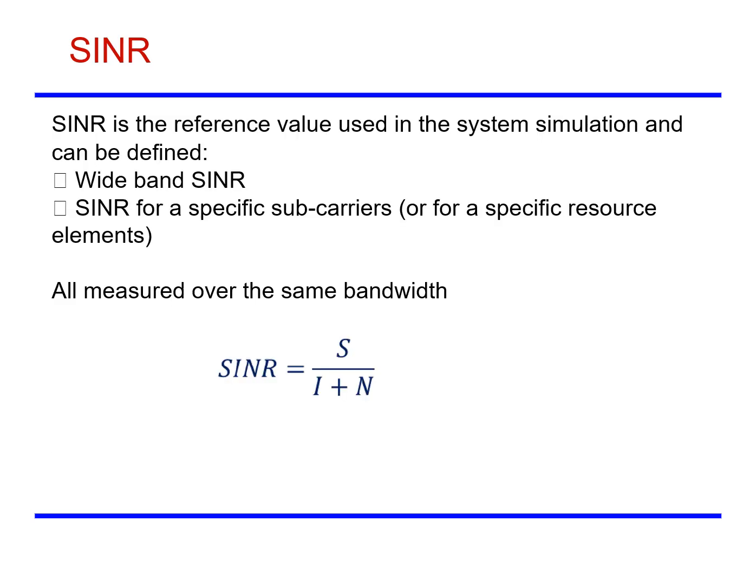SINR is the reference value used in the system simulation and can be defined as wideband SINR and SINR for specific subcarriers, all measured over the same bandwidth. SINR equals S divided by I plus N.